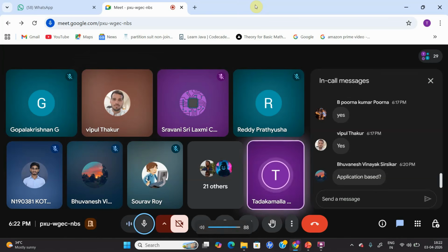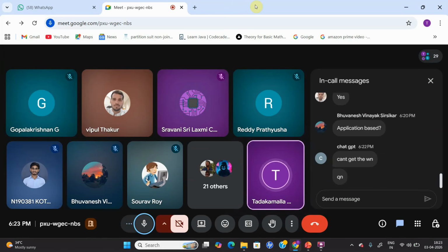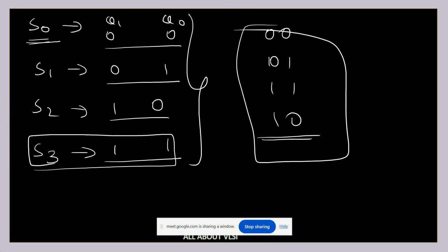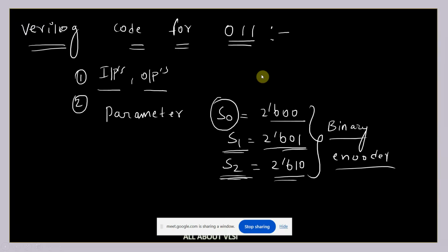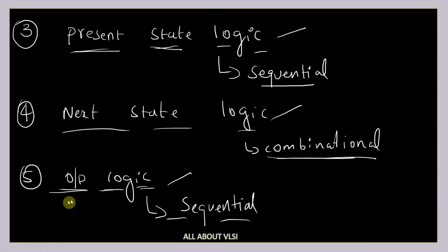Okay. So basically, it is not going to work because the next state logic is a combinational logic. So your counter is not going to increment as you have expected. The question is simple. Verilog coding has three blocks, right? Present state logic, next state logic, output logic. Let's say we have some requirement for the counter incrementing, and we have written the counter incremental logic in the next state block. Is it going to work or not? That is my question.